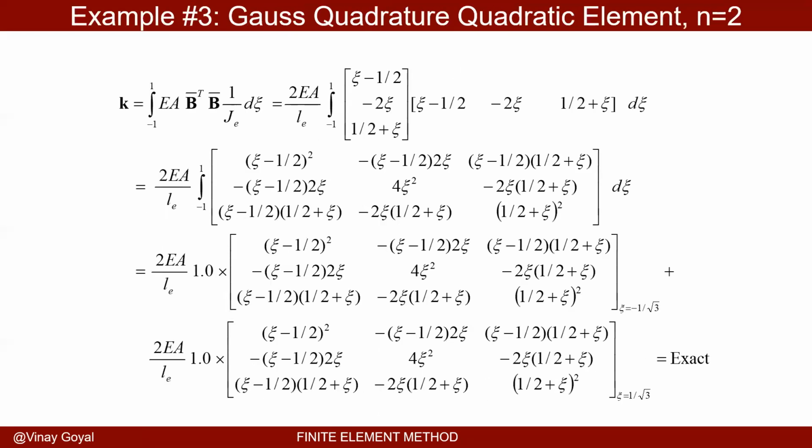So with that said, I want to thank you for listening to this particular lecture. I think it's very exciting that we can take a governing equation and divide the domain. I don't care what shape, I don't care how you divide the domain, because at the end of the day, I plan to take every element and map it to a standard element size. In this case it goes from -1 to 1, and the integrals go from -1 to 1, which allows me to use this Gaussian quadrature approach to numerically solve integrals.